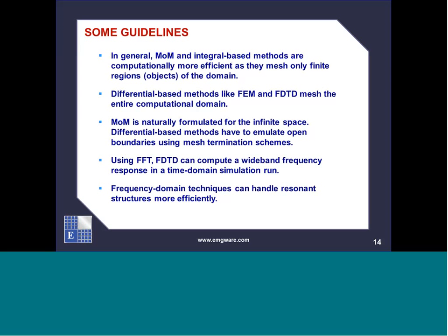But on the upside, techniques like finite element and FDTD are more general. They can do much more complex geometries than method of moments. Also, using fast Fourier transform, FDTD can compute a wideband frequency response in a single time domain simulation run. So when you are working with wideband structures like filters, the method of choice would be FDTD, because with one single run, you can get the entire frequency response. On the downside, FDTD has problems with resonant structures, because the energy basically oscillates inside your computational domain, and for resonant structures, frequency domain techniques like method of moments or finite element can handle the problem more efficiently, from a computational point of view.